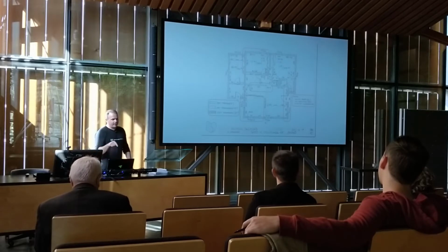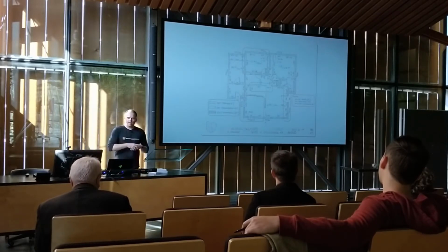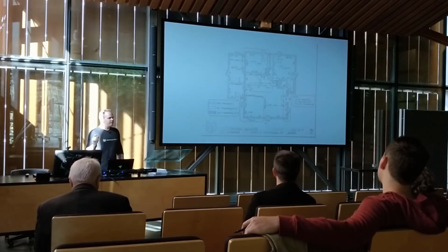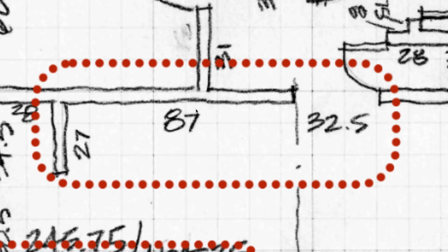This is where I landed, and I have a very specific reason for all of these different techniques: I'm planning down the road that these field notes are going to get scanned into SketchUp, and I'm going to build my existing conditions model right on top of my field notes. The way that I take these notes is going to be super helpful if I'm just aware of it up front. So the way that I record measurements is always in decimal inches.